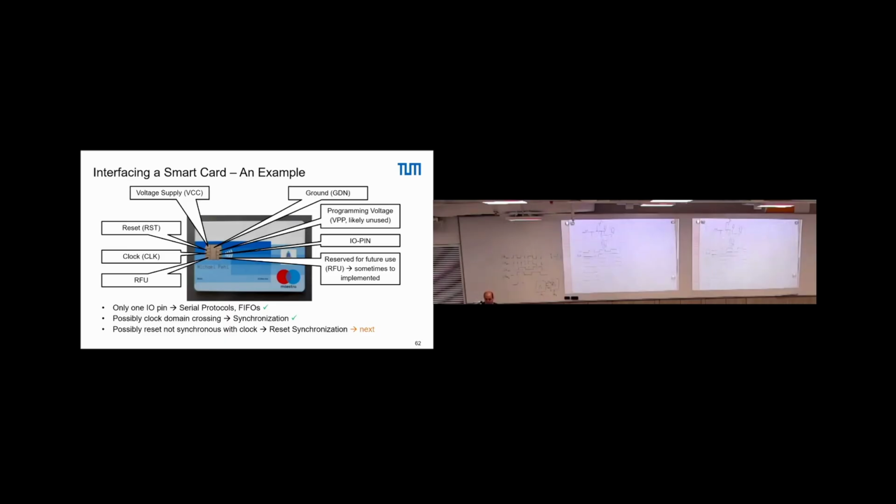Now, obviously this is driven by our reset signal here at the input. So we have it at 0. We can go down here a little bit, it's just where the reset signal is. Now we see here a certain delay by this capacitance, a certain delay by this capacitance, 2 times the delay. We have effectively a set slightly delayed compared to that. Then it goes up.